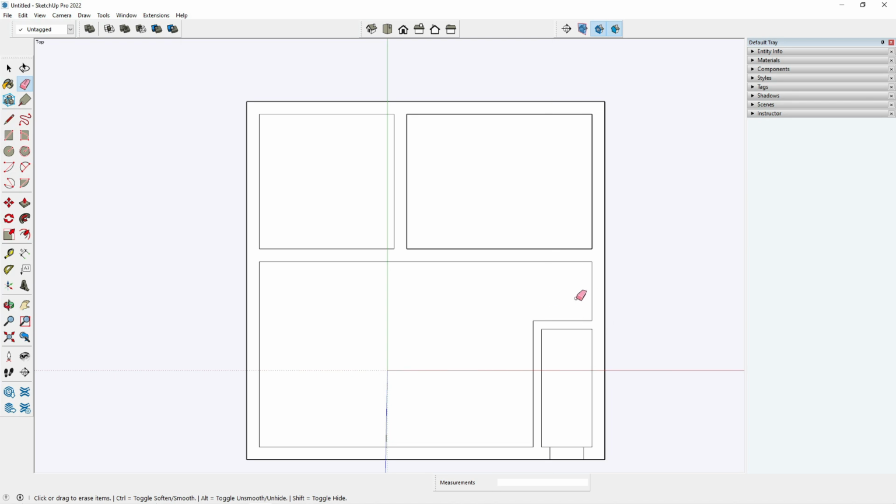Then we had one window over here. We'll leave a 6-inch gap from both sides, since they have not mentioned the window size. One window over here. If you see, the window comes to around 2 feet 6 inch, which is correct. And we had a main entrance door over here. I'm going to leave 6 inch, and put a 4 feet entrance door.